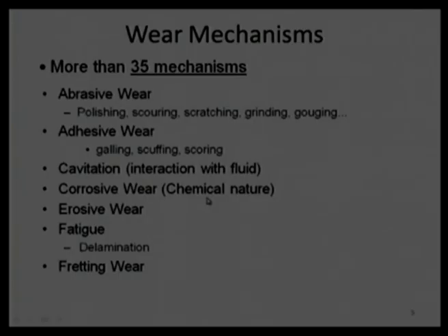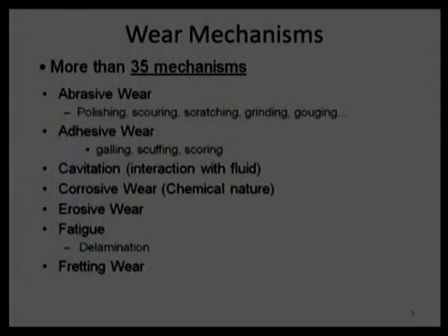That means initiation happened because of the chemical action, and finally the removal of material happens because of the mechanical action. There is another kind of wear which we know, the erosive wear. It happens again because of liquid, or high velocity liquid, or high velocity particles also. Particles are generally more common to cause erosive wear. Maybe a typical example is fly ash. If high velocity fly ash impinges directly on the surfaces, it will cause excessive wear. Another wear is fatigue wear, and one category of fatigue wear itself is delamination.